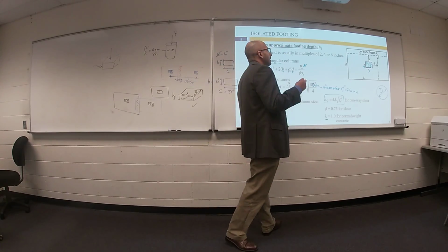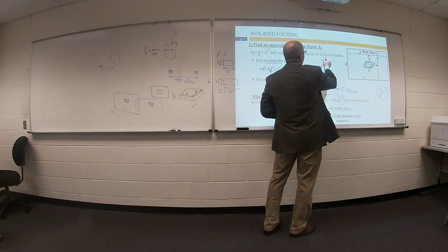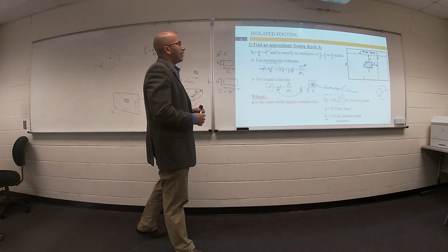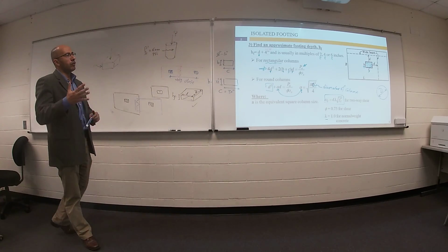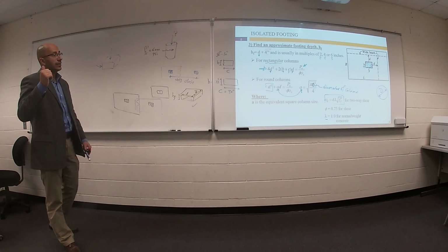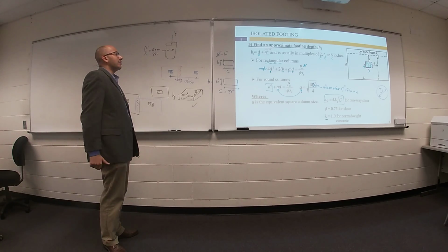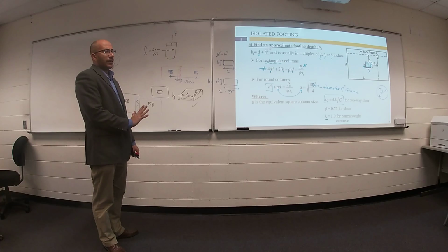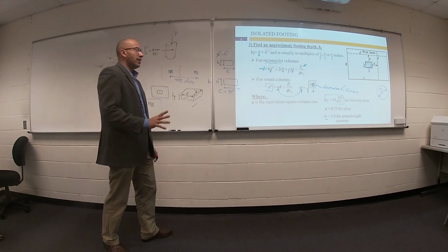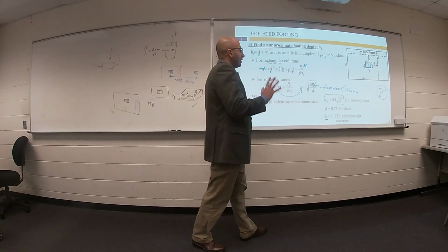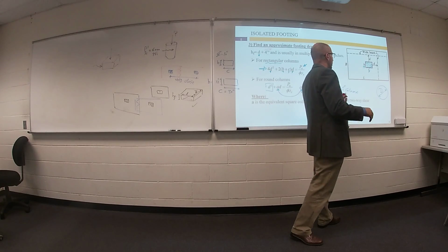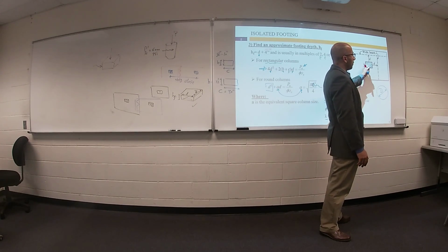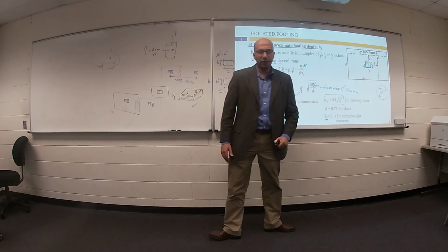Remember, it's recommended to make your total thickness a multiple of 2, like 4, 6, 8, an even integer. Any questions so far? It's required, not just important, to design your column before starting to design the foundation.